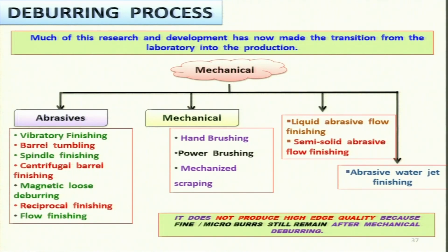It does not produce high edge quality. Whatever methods are shown over here, the majority of them do not produce high edge quality, because fine micro burrs still remain after mechanical deburring. That is why normally people recommend electrochemical deburring for high or better performance.